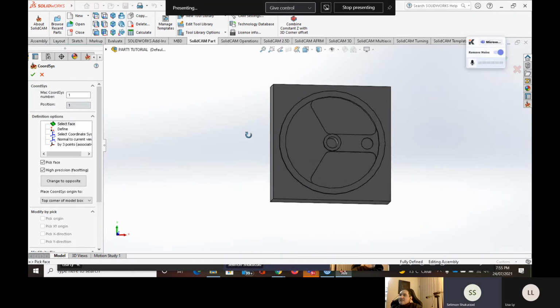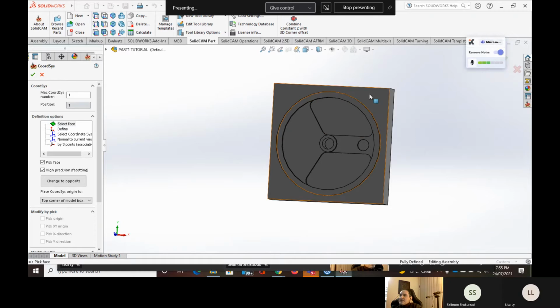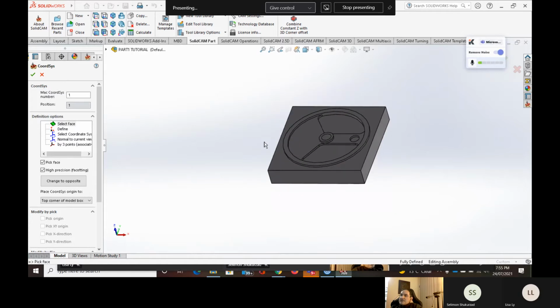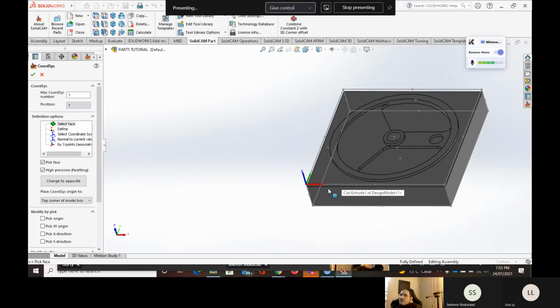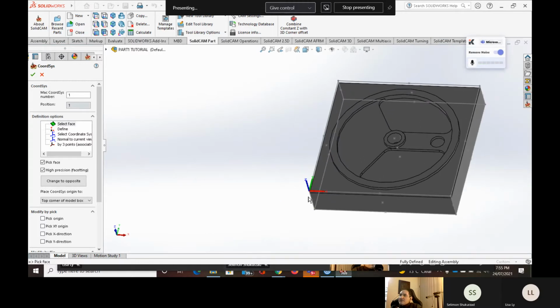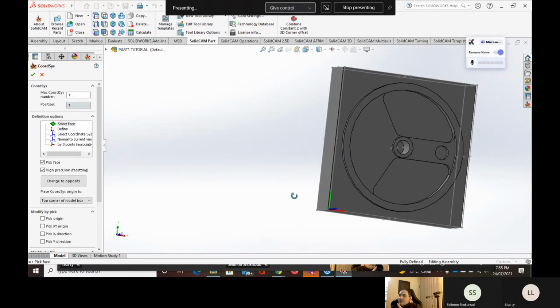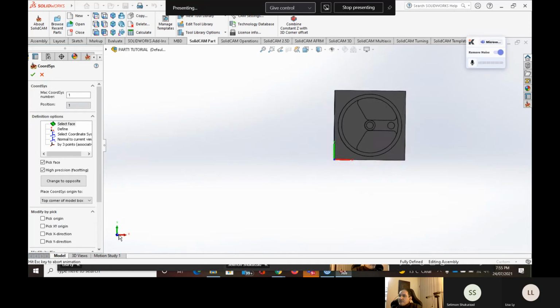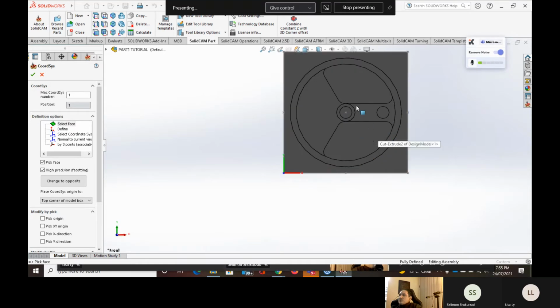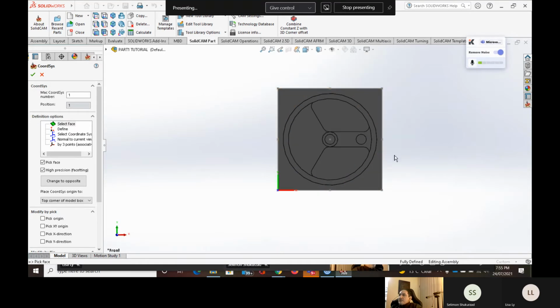But bottom right. Yeah, as we mentioned earlier, it's going to be the bottom left at the top face. So the top face of this work part is going to be the highest surface we have, which is this one. By default, because usually we always prefer to have the datum point at the top lower left corner. So again, looking at the part from the top, it is going to be at this position. Now, I explained to you earlier why we have it at this position.